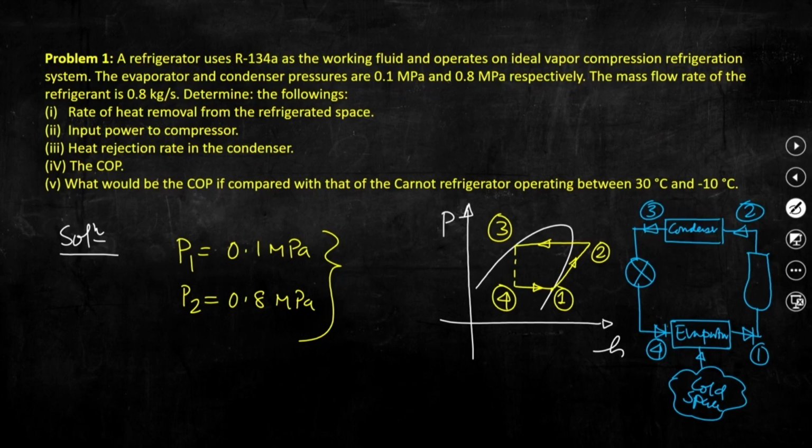Now, if we try to recall, in the last class we also discussed that whether we would like to calculate the power needed to be supplied to the compressor to drive it, or the amount of heat that will be extracted by the evaporator from this cold space, essentially per unit mass flow rate of refrigerant it is the enthalpy change across those devices. So, across those devices or components, change in enthalpy is a measure of the heat or work interaction.